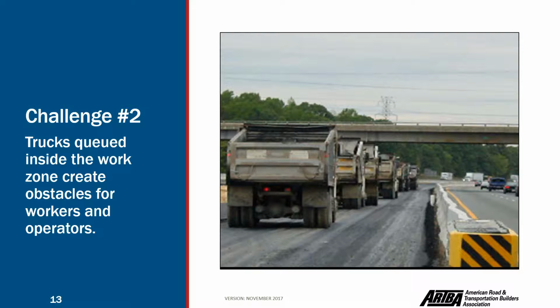So another challenge that we have with access and exit zones is trucks queued inside the work zone create obstacles for workers and operators. Okay, look, again, we are talking about blind spots. In this queue of trucks, we can realize we have multiple blind spots, and we don't want workers to walk in this area.